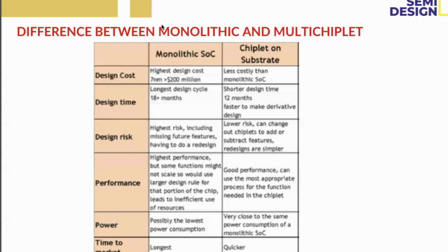Can you repeat, ma'am? Yes, we have different stages of pipelining, like 3-stage, 5-stage, 6-stage. Now we have seen 5-stage: fetching, decoding, executing, next memory access, next write back stage. That is one advantage. If we have a write back stage, we can write to the memory or any existing register. If you go for a 3-stage pipeline, we have only fetching, decoding, and execution, with no memory or write back stage. So those are limitations of the 3-stage.